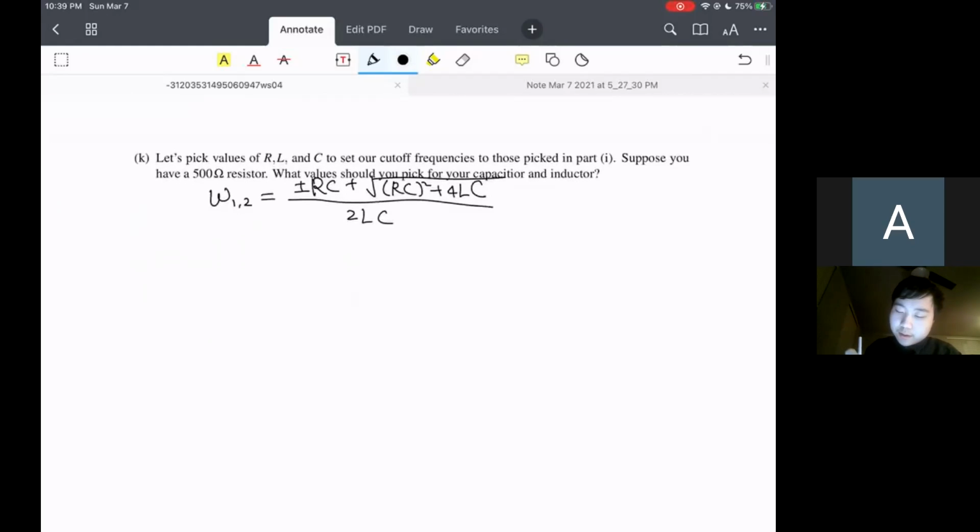So let's say we want to have our low cutoff frequency at 6 Hz, and our high cutoff frequency at 14 Hz. If you pick some other frequencies, that's probably also fine, but the effect of this filter is probably not going to be as effective.